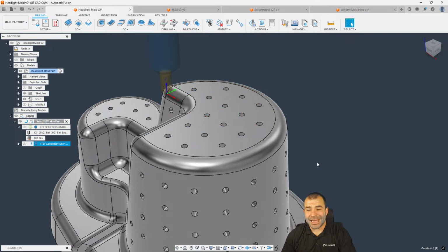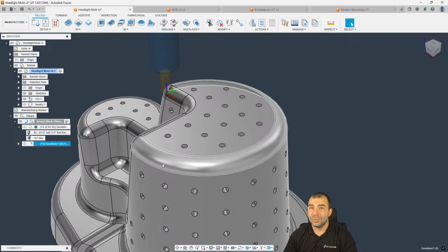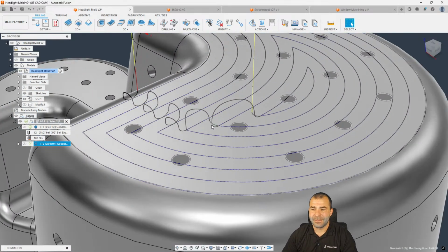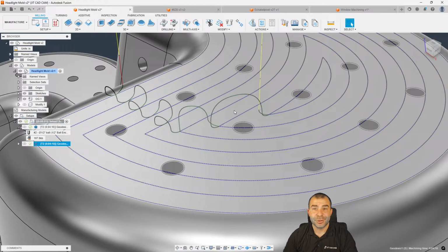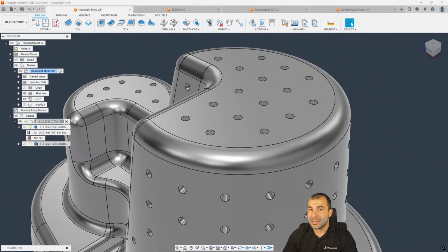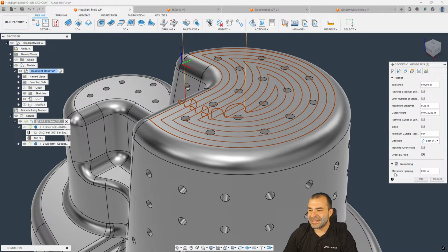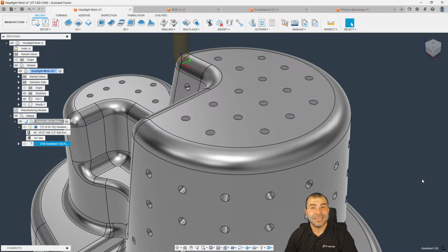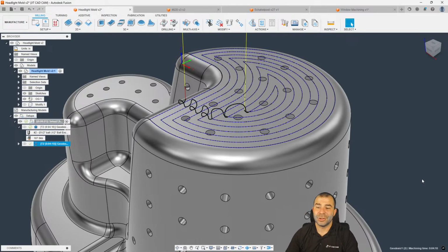What smoothing is designed to do is basically reduce your points based on a certain amount of area. Now, what you're seeing here for smoothing on geodesic is a little bit different. It's not smoothing based on how much you're allowing a point to move to get it in line with the other points. What we're actually doing is saying how far away can one point be from the next point. Normally you're trying to reduce points, and if you wanted to reduce points, you would have to turn up your smoothing dramatic amounts, because again, it's based on a spacing scenario. It's not based on the traditional approach.